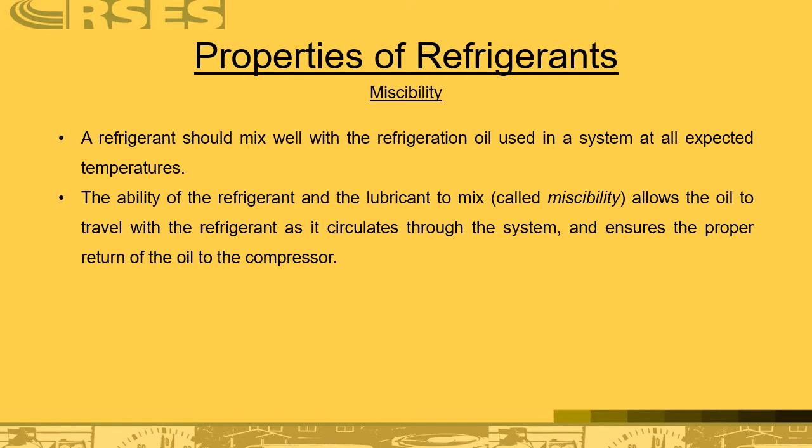Now, the one thing I want to talk about on miscibility, on a quick note, we're utilizing POE oil now in pretty much all compressors. We've eliminated mineral oil, we've eliminated alkylbenzene oils in new compressors. We found that POE is the oil of choice to make this happen with the refrigerants that are in use today. The downside to this is POE oil is like a sponge. It has the ability to absorb moisture anywhere. And for that reason, POE oil is never shipped in a plastic container.